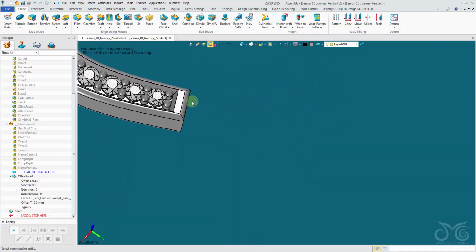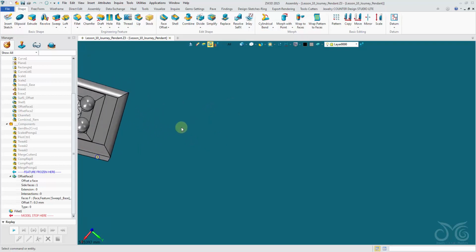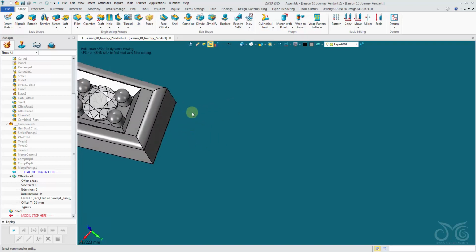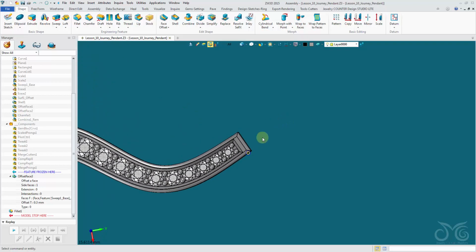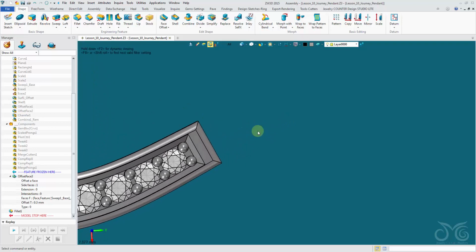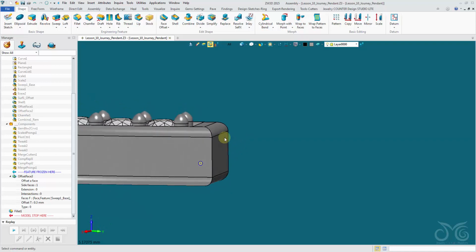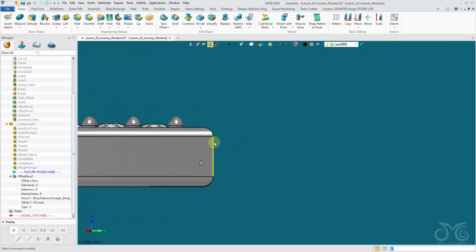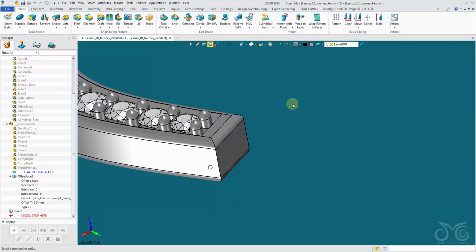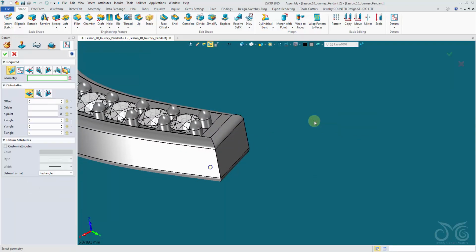Now we want to place our gemstone and bezel at the end here. We're going to place, I think, about a 2.5mm diameter round gemstone, which means I want to place it on a datum which is coming off from here about 1.25mm, so half of 2.5. So I need a datum to place my stone on. So I'm going to insert datum.